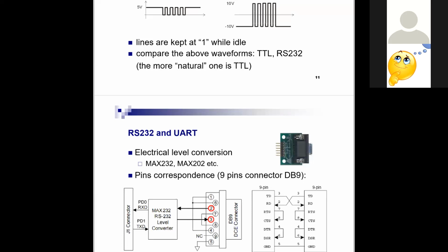But why is RS232 still popular now? There is handshaking while I am transmitting and receiving. The handshake signal is between the transmission and reception. So automatically RS232 became very popular, and even now, in spite of its invention stage, it is still popular because of its nature. Maybe the size keeps getting reduced, but it is still popular due to two reasons: one is the handshaking signals, and another is the level of voltages.